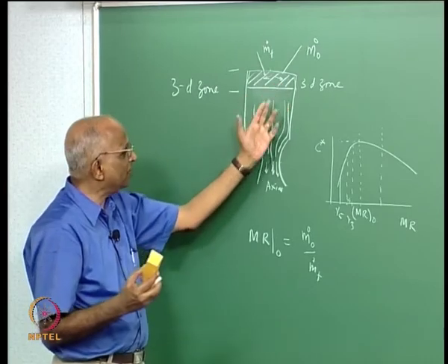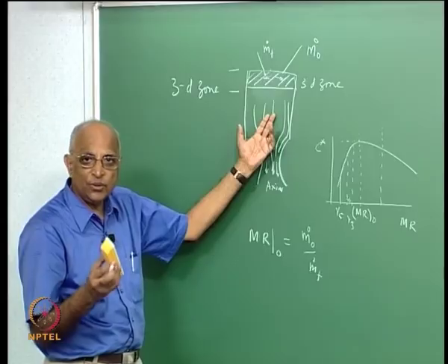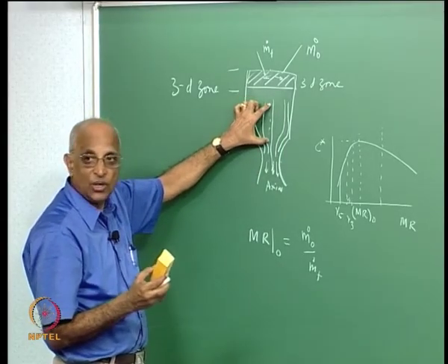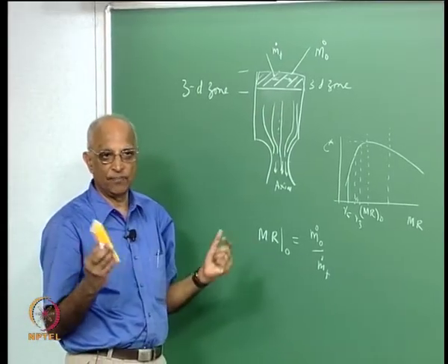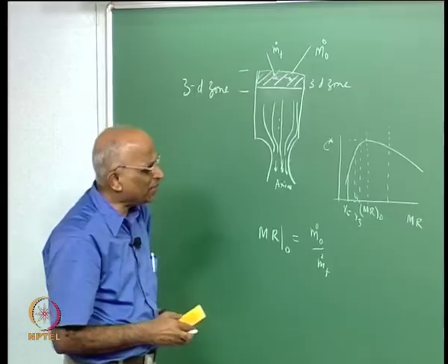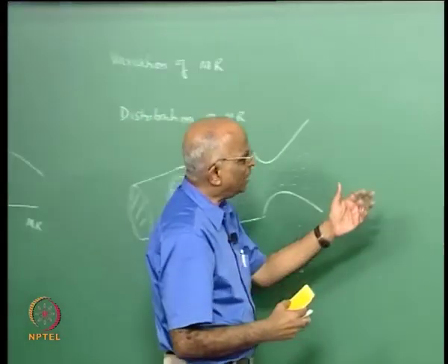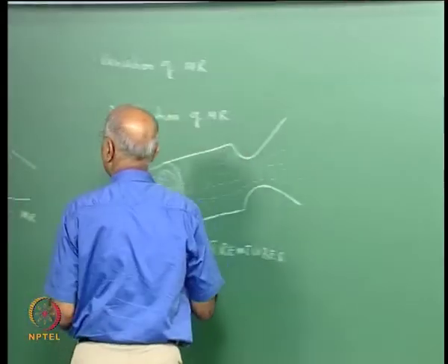And the assumption is individual stream tubes do not mix with each other, and why do they not mix? Because the length is short, the turbulence still does not develop totally, and therefore mixing between stream tubes is not there. And now how do I distribute? See, we have done the problem, but can I characterize a distribution parameter? What should the distribution parameter consist of?